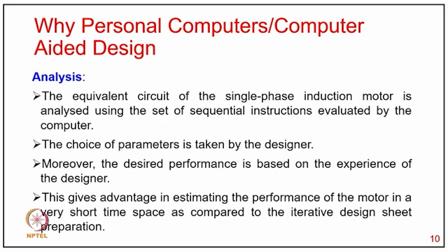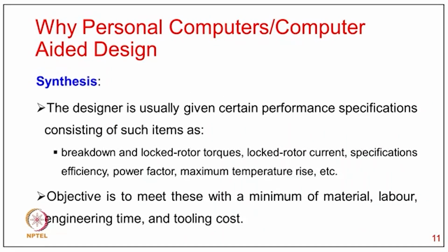Now coming to the analysis part of the analysis based design approach, the equivalent circuit of the single phase induction motor is analyzed using a set of sequential instructions evaluated by the computer and the choice of parameters taken by the designer. Moreover, the desired performance is based on the experience of the designer, and this gives the advantage of estimating the performance of the motor in a very short time as compared to the iterative design sheet preparation.